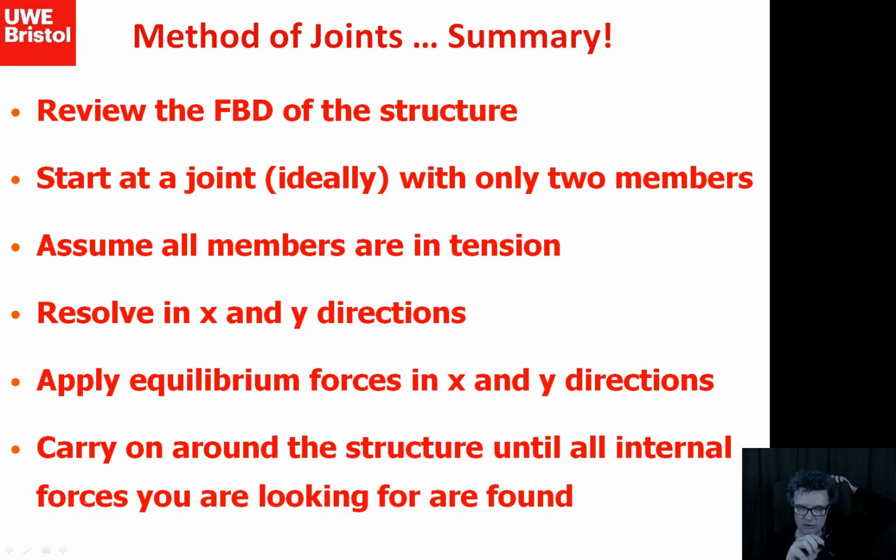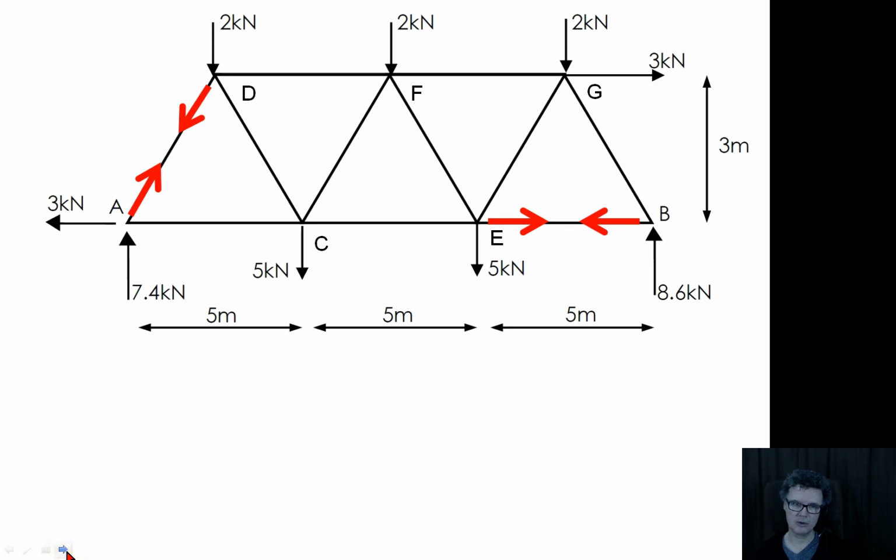Those forces where you've cut through the members, you've exposed their forces, and we say that their forces are going to be going in the direction of the members, and also going away from the joint. We can then simply resolve things in the x and the y directions. We've got two unknown internal forces and two directions to work with, so we've got enough to solve them. And then you carry on around your framework until you find all the values you're looking for.